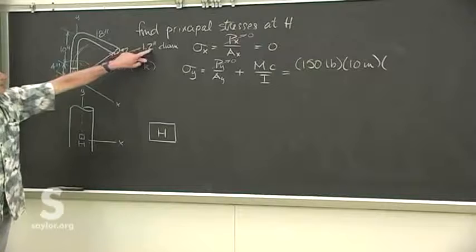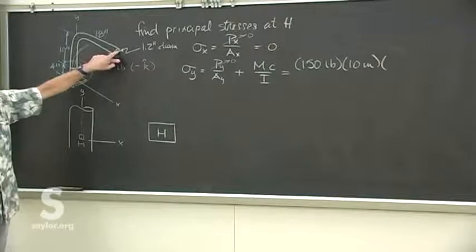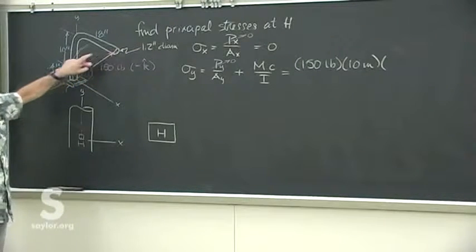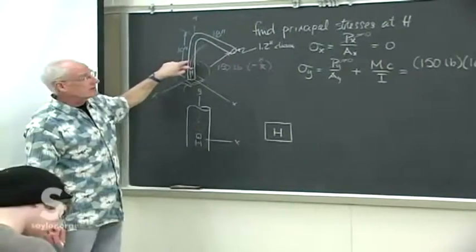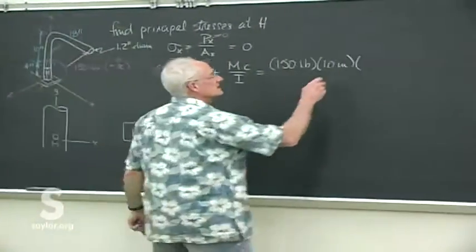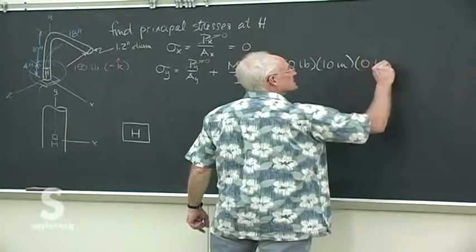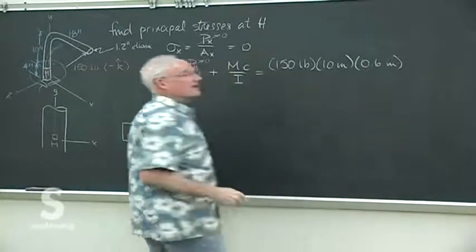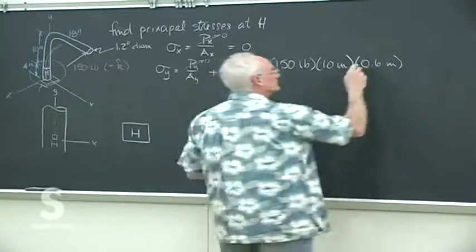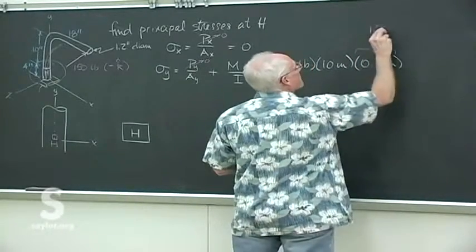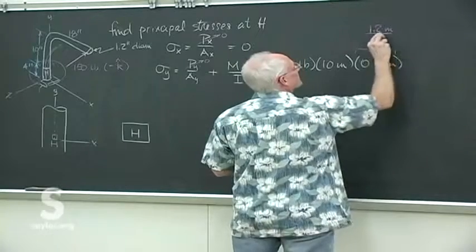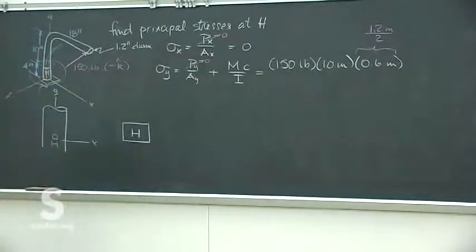The diameter is 1.5. C then is the radius. It's the distance from the center. Because of the symmetry, that's the neutral axis, goes right through the center. We're distance 0.6 inches away from that, half of the 1.2. So, simply the radius.